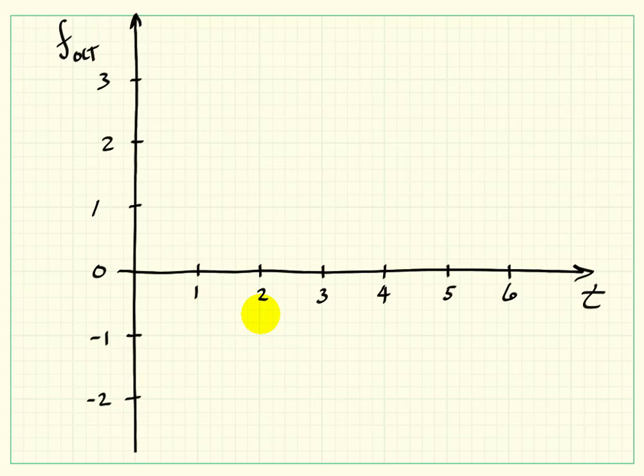Here's an example of additive synthesis that proceeds from the design of an idea for a spectrogram. And I would like to design a frequency trajectory such that it starts at a reference frequency, that's my 0 octave, it moves up 2 octaves, and then it splits into 2 partials where one goes up an octave and the other one comes down an octave. And then in turn, each of these 2 partials is also divided in 2.